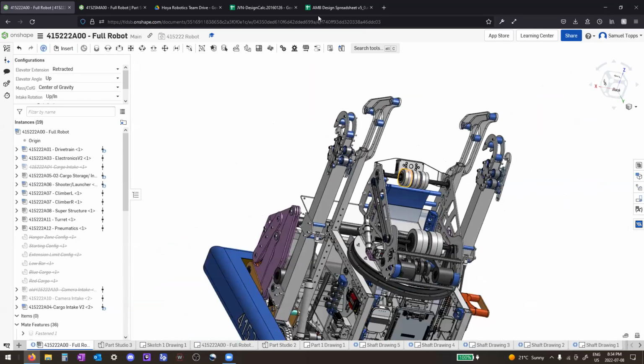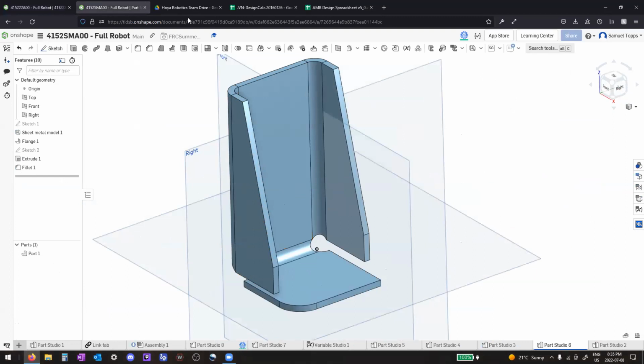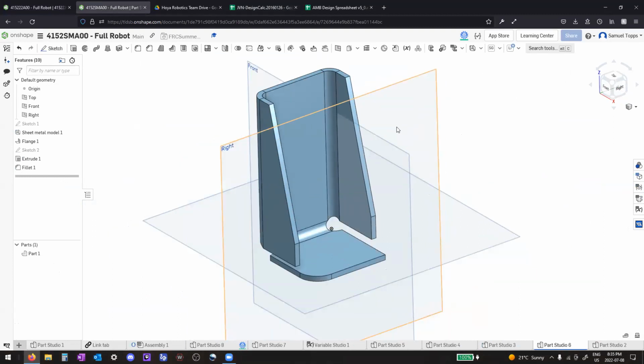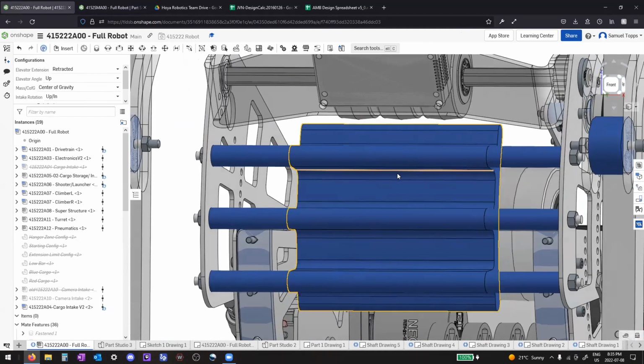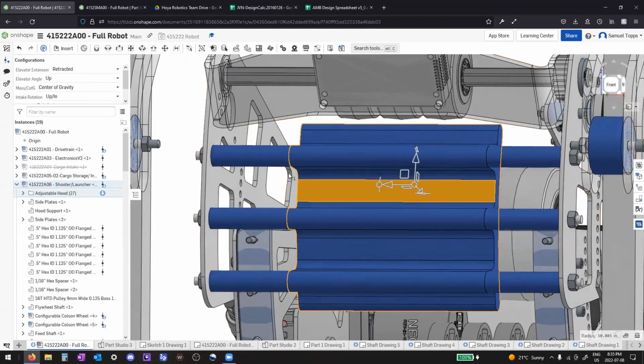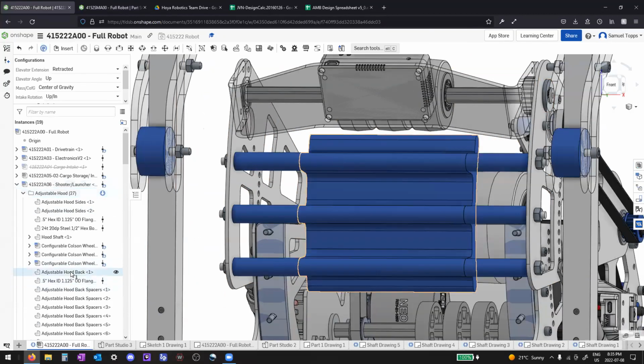I'm going to jump in there with the 3D printing part. Often it's beneficial to break a 3D printed part into separate parts. If you think about how the 3D printer works, it's basically putting down layers and layers of plastic. So with something like the hood, it might make sense to print the hood on its side and then have 3D printed spacers, which I think we've got there.